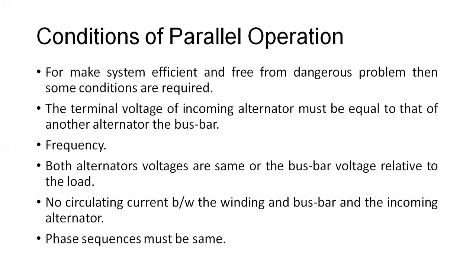Irrespective of the load, all voltages should match, so that there should not be any circulating current between the winding and the bus bar and the incoming alternators.